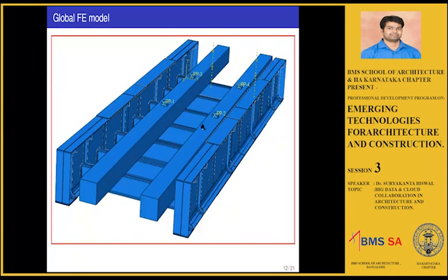So we did the global FE model, including the timber, or removing the timber also. We had all the components of the bridge, including the L stiffeners, T stiffeners, the rectangular stiffeners, angles, everything, except the rivets. So we did not include the rivets in the global FE model.